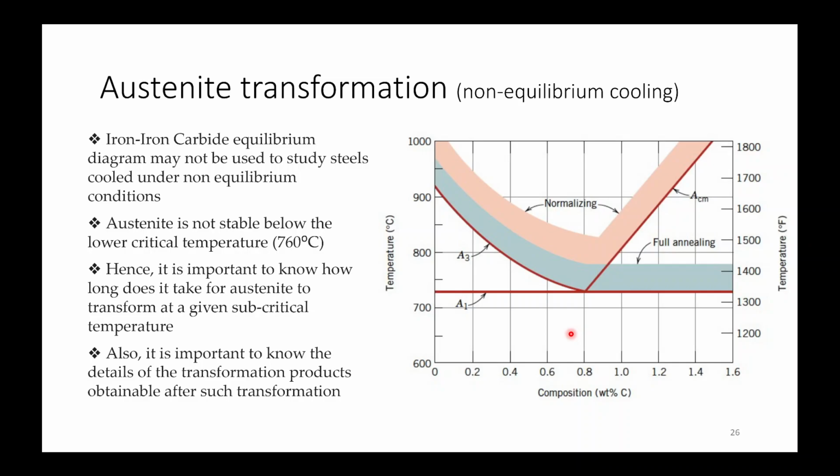The interface is actually a junction. Maybe that leads to a change of orientation of the atoms at the boundary. The compositional difference cannot be represented by drawing a line. If you are moving in a particular direction, Fe3C has a different concentration of carbon, and alpha has a different concentration of carbon. That's why they are different phases, which won't be shown in your phase diagram.